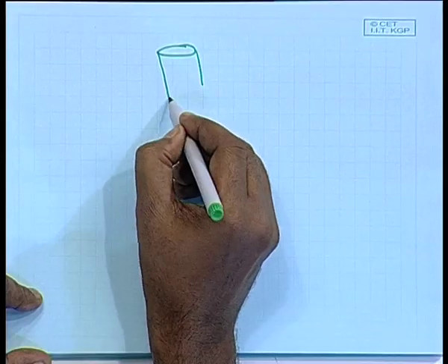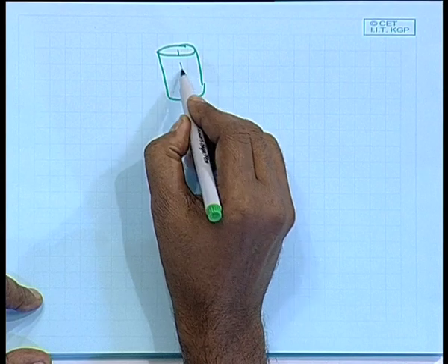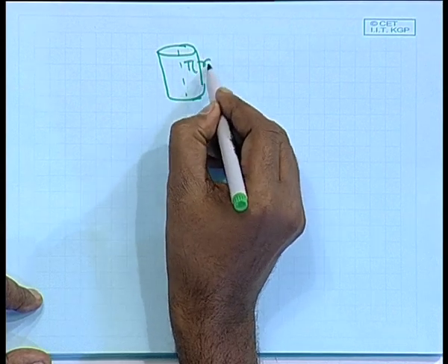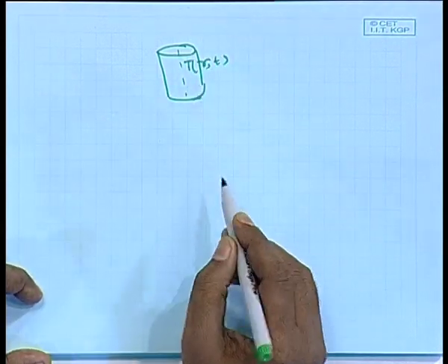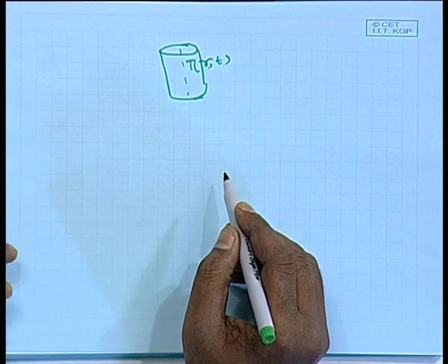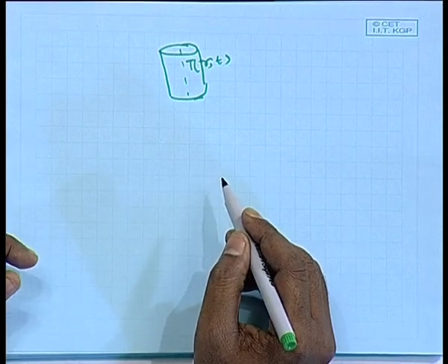Now, more often the steady state problem may not be important; the transient problem is important. Like the example I was giving, you have a nuclear fuel element whose temperature is a function of r and t, and the z dimension is so long that the variation of temperature in the z direction is negligibly small.